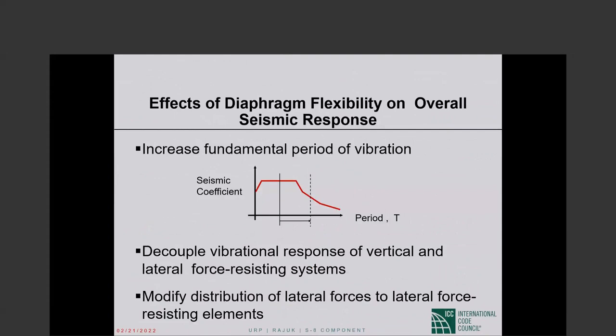Now, if diaphragms are flexible, flexible diaphragms typically are, take the parking structure. A parking structure bay is about 60 feet wide. That doesn't vary, could be 62 feet, but something in that range. In the other direction, you go these days 300 feet maybe. Not always 300 feet, but you can go up to 300 feet or more. So that gives you a diaphragm aspect ratio of 300 by 60. And that is a very flexible diaphragm. The span is long, 300 feet, and the span to depth ratio is large. 5 is very, very large. Below 3 is kind of not very flexible.